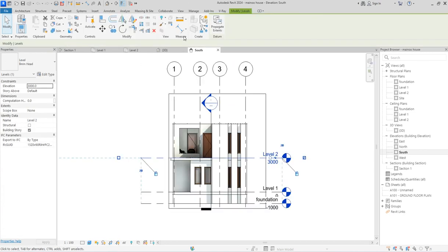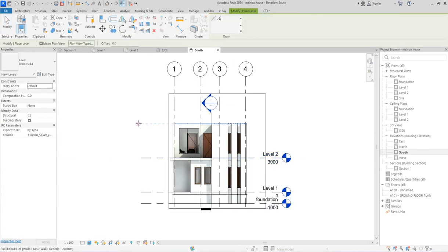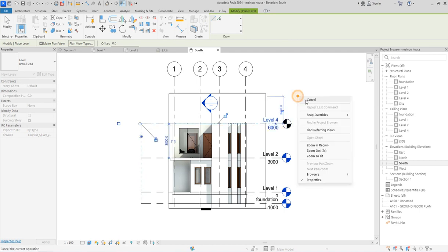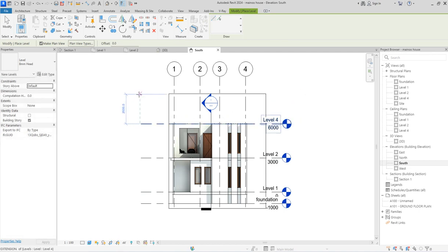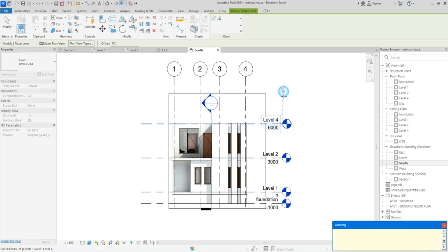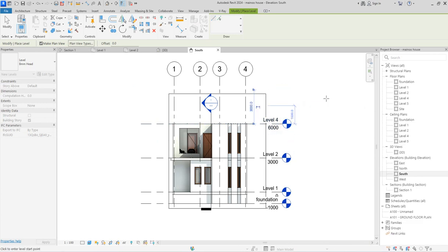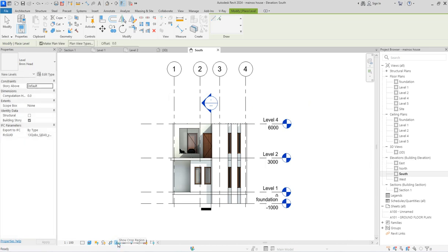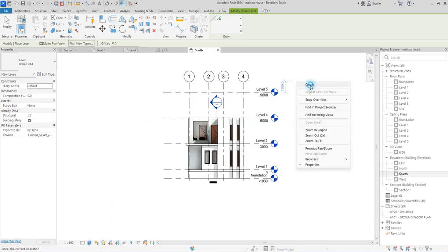So click here and say create similar. You click on this create similar. You can create more if you have it. It's not displaying because of the crop region. So if you have such an issue, just toggle the crop region here. So here now you've seen it within the display.